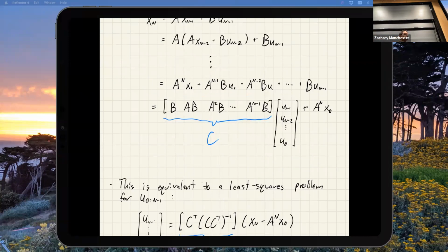Why don't we just use this? In continuous time obviously we can't do this, but since we're working in discrete time, why don't we just use this to find our mu vector for some finite horizon? Yeah, so this is a good thing to ask. This is equivalent to an LQR problem with Q and R equal to identity, which is not necessarily obvious, but if you work this out a little more, that's what this is.